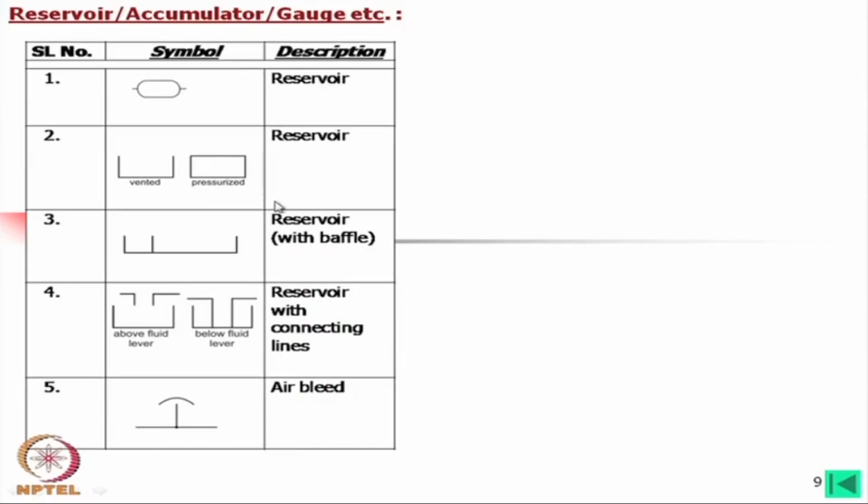Normal venting is not there. So, for that pressurized we can show that the reservoir is like this. Now, this reservoir is baffled. What is a baffle? Usually you will find inside the separator. So, first oil is coming over here and then it is going this side. Many contaminants will remain at this side and suction is usually on the opposite side. So, return on one side and suction on the other side, and again such baffles are like that.